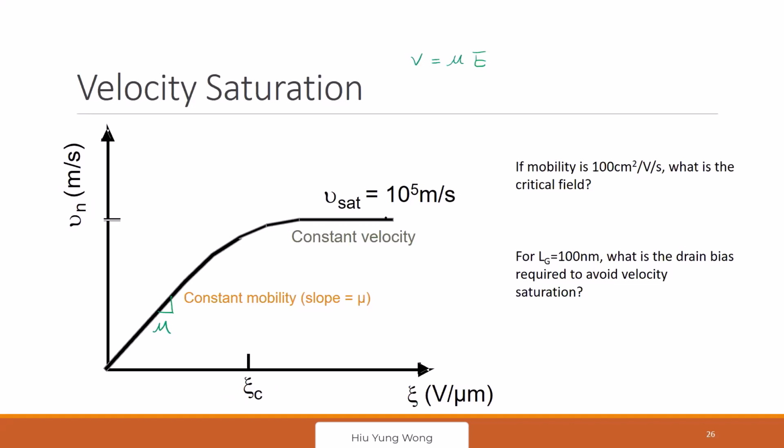It's like you enable it to do something called optical phonon scattering, which it cannot do when it has low energy. Okay, just like a person, right? You keep it growing up, you thought that it's earning more money, but then when that guy grows up, it has more spending, unlike a baby, which only eats and drinks and sleeps, right? So there is something called saturation velocity, the maximum that you can get to, okay? And there is an electric field. Once you reach there, you basically just travel at saturation velocity.